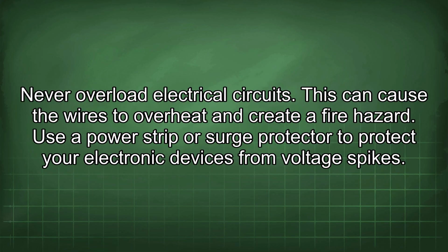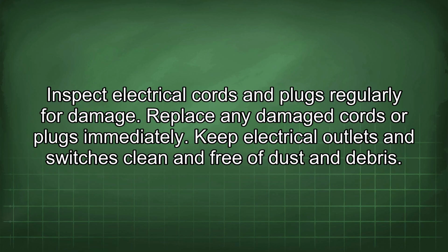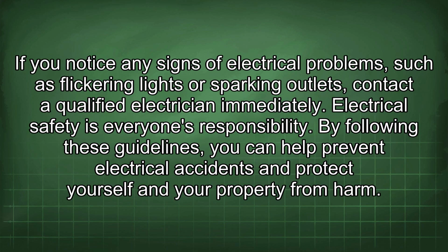Never overload electrical circuits. This can cause the wires to overheat and create a fire hazard. Use a power strip or surge protector to protect your electronic devices from voltage spikes. Inspect electrical cords and plugs regularly for damage. Replace any damaged cords or plugs immediately. Keep electrical outlets and switches clean and free of dust and debris. If you notice any signs of electrical problems, such as flickering lights or sparking outlets, contact a qualified electrician immediately.